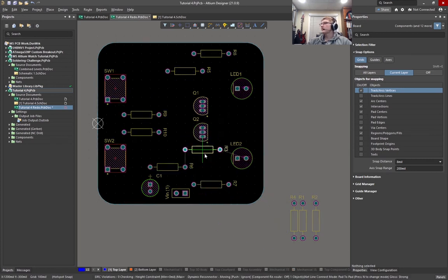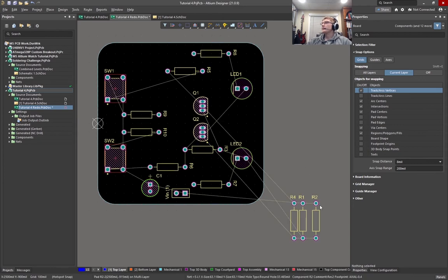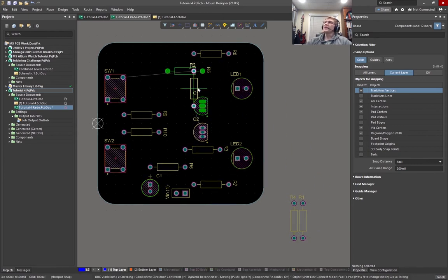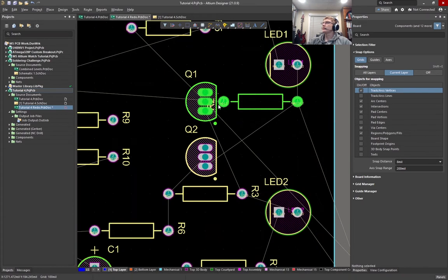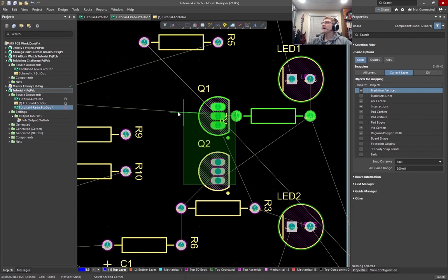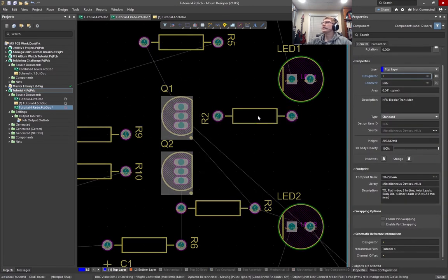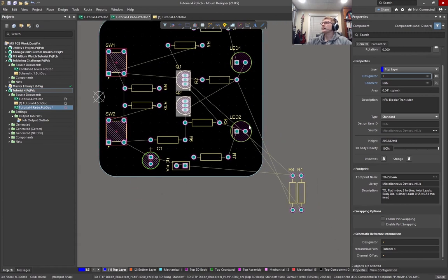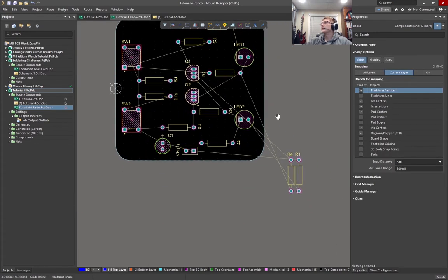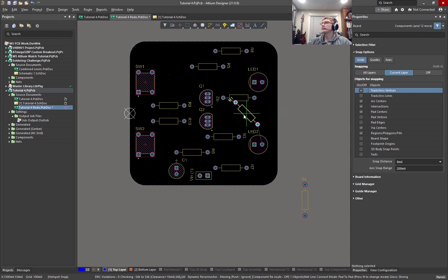And so let me talk about some other considerations. You want to think about where your sensitive signals are. For example, if I have some very important communication line, I would make sure that I don't force myself to have to route it next to very noisy or very high current lines. I wouldn't want to put sensitive lines near things that are driving motors or something like that. That wouldn't make a lot of sense because I could get some interference going on between those traces.